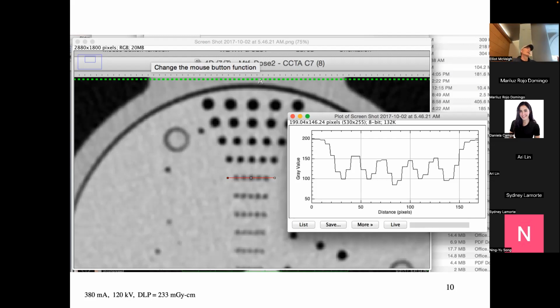So you have a transmit coil which can produce ridiculously high voltages and currents, and a receiver coil that's usually down in like millivolts, right? And so if all of a sudden you had signal that was large enough to be volts, it probably would just blow the thing up, right? Which we've done before. If you don't decouple your receiver coil from your transmitter coil, you can transmit directly into your receiver chain, and that will just fry it with too much signal.